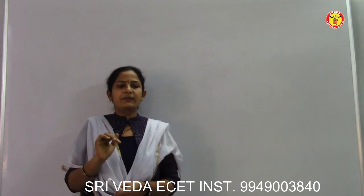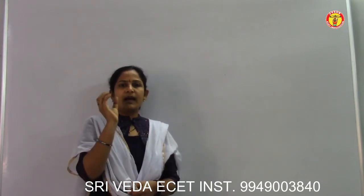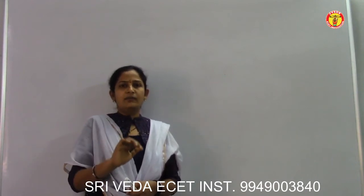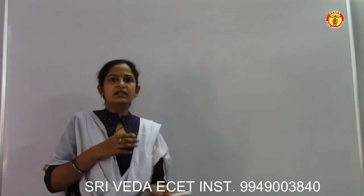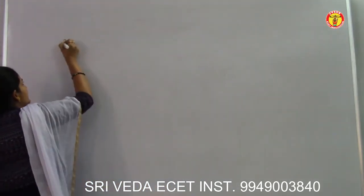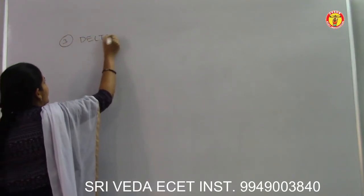And in DPCM, as we are taking only the difference between the two signals, the bandwidth is reduced to a limit, but the system was very complex due to the use of a filter. So now we will learn delta modulation. This is the third type of modulation we use in digital communication, that is delta modulation.